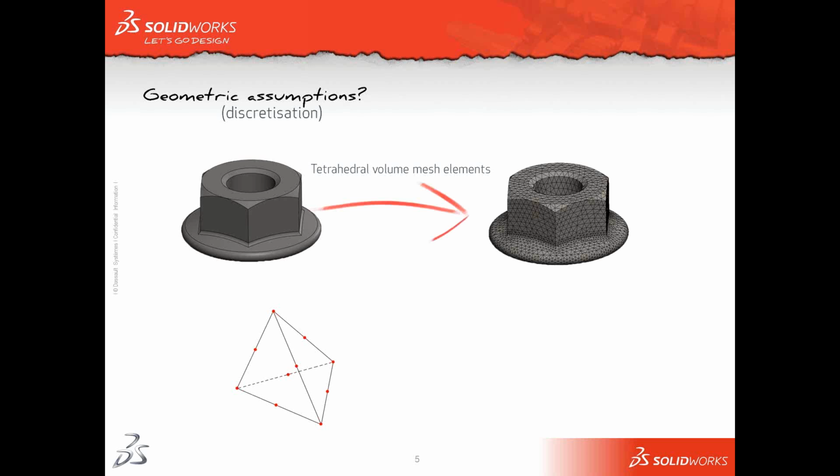So here on the right hand side you should see a pictographic representation of our meshed solid geometry. And like I said, what SolidWorks is going to do is determine the stress/strain results at each of the nodes on these elements. If you can imagine, each of these nodes can move in the x direction, y direction and z direction, giving it 3 translational degrees of freedom.